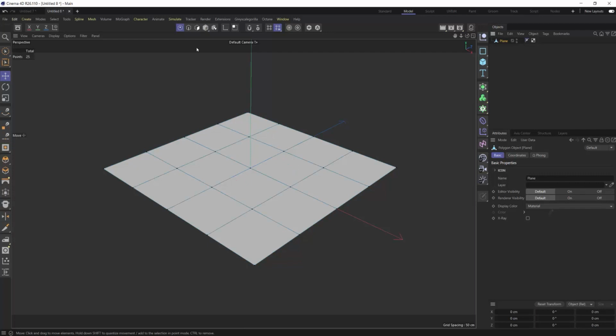Now for this, have you ever wanted to create a circular shape out of one of these squared polygons? You'll see this a lot in sci-fi or tech parts and stuff like that. Think about the speakers on your phone, something like that, that radial grid. Let's try to create something like that. And you can do it in a handful of different ways. In this Intro to Hard Surface Part 1, I'm going to show you how to do it with the bevel tool. So I'm in point mode, select this first point here on our plane, and let's go into our bevel tool.